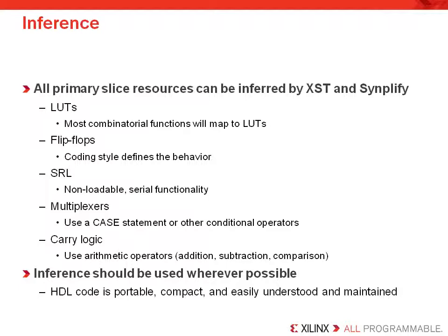Likewise, the shift register LUT is non-loadable, has no reset, and only supports a serial functionality. So if you code for a parallel read, you will get a pure register implementation, and this may not be what you expected. Similarly, muxes should use a case statement, and carry logic should use the proper arithmetic operator. Don't code for the XOR functionality and expect it to target the carry logic resource.